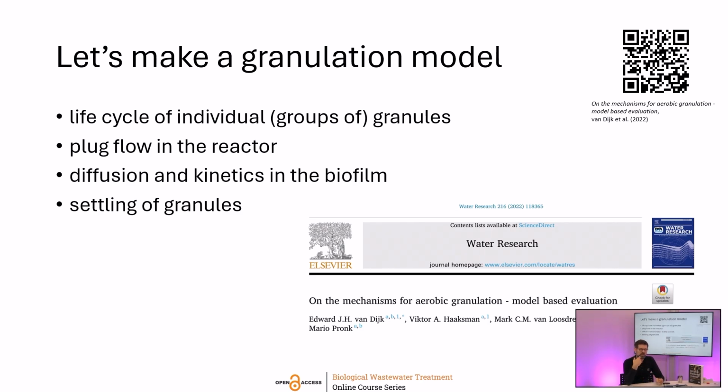We really know that the current reactors are plug flow reactors where we feed from the bottom, and that is important. That's how we also invented granular sludge at TU Delft. We really wanted to have the biofilm kinetics with diffusion and all those kinetics. And we already knew that granules settle at different rates depending on their size, so we also wanted to have that in the model. So we made a combined model of all these processes to see if we understand what is happening and if we could describe that granulation process.